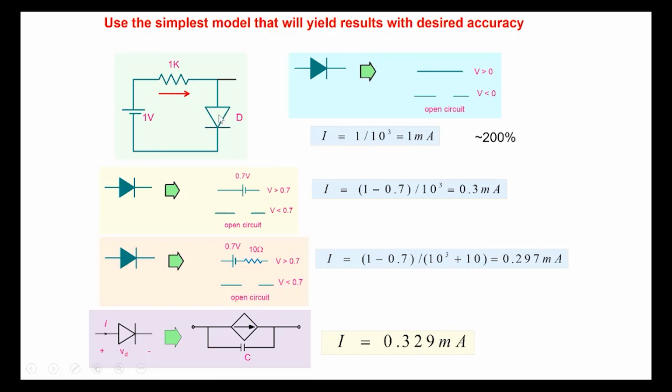And which is obvious because we said that when the voltages in the circuits are close to the diode drop, you should be careful and not use very, very simple models here, right? So 200% error here, 8.8% error here, 9.7% here, and the final value here. And the reason why we didn't get a very good answer here is because there's a problem with the model here. We can build a better model and get a better result for this particular case. So even in this case, this kind of a model gives us error less than 10%. So we are okay with this constant diode model here.